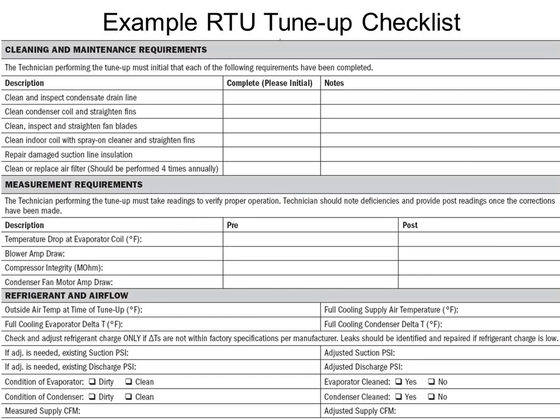And then we want them to actually clean stuff, right? Clean the condenser, clean the evaporator coil. Why does that save energy? Well, dirt acts like an insulator. So if I have dirt on my coils, I'm reducing the heat transfer, which means my compression has to run longer in order to transfer heat, right? So I want clean evaporators and clean condenser coils in order to optimize my energy and optimize my BTU capacities. So that's the kind of stuff that we're typically asking for.